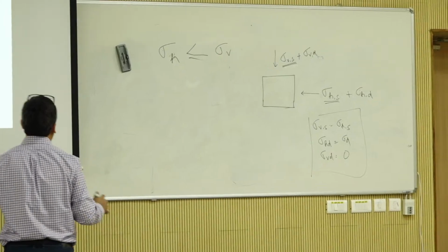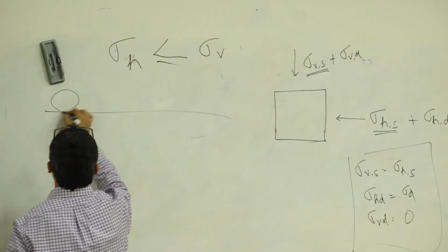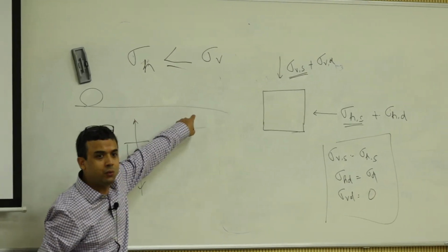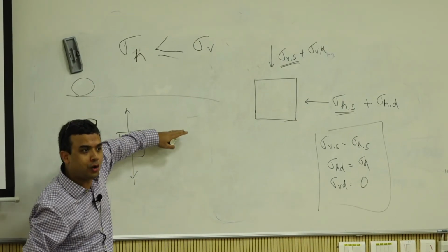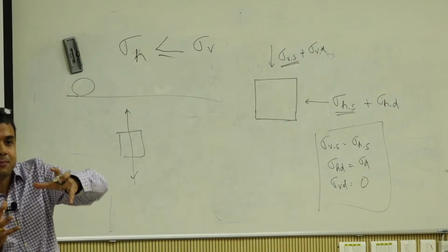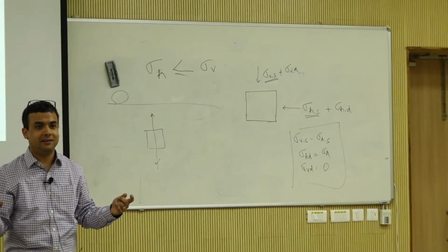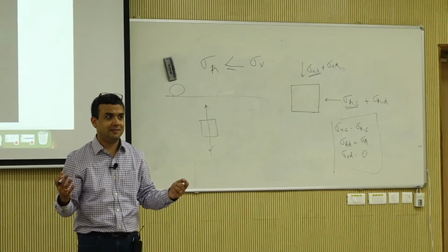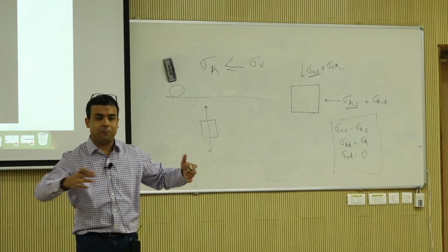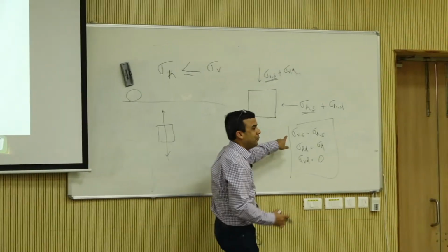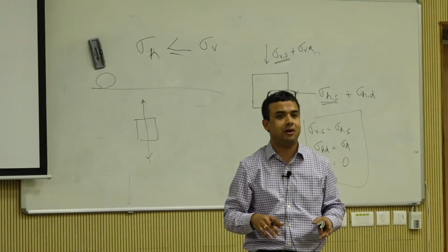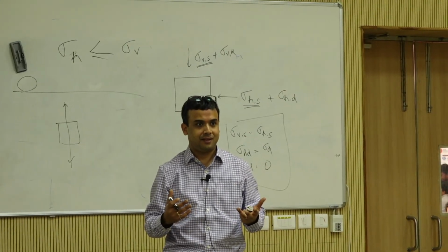What did I say? When the wheel moves, what happens to the principal strain's direction? It moves. To test it in the lab, you would have to rotate your specimen. How possible is that? It's not, right? It's an unbound specimen. You can't make it horizontal, it's going to collapse. So might as well develop a test system which has independent control in my vertical and horizontal, and now I can do everything and anything I want, right?